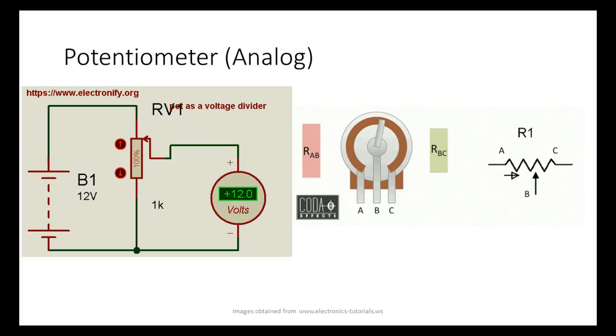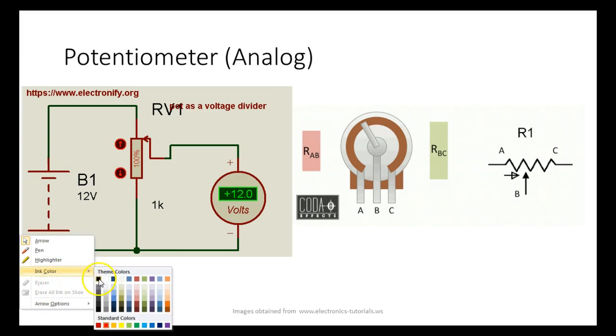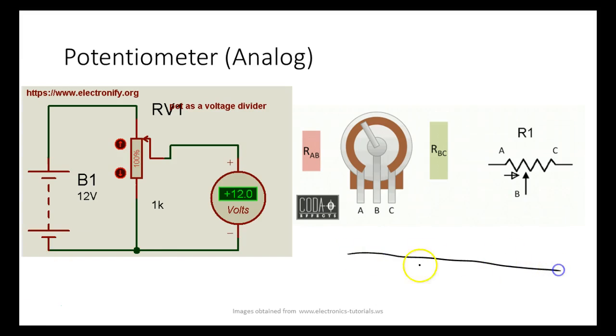In fact, I've got it on the power pin. So this is going to give me a voltage that's proportional to wherever that wiper's at. Now, we don't show that, but we could just as well take that resistor and spread it out like this, right? And then we have a wiper coming right here. As it moves across this, this is what we call a linear pot, a straight line pot. That's what's on the gantry robot on the right of the Amatrol line, across the top over there. That's a linear potentiometer.